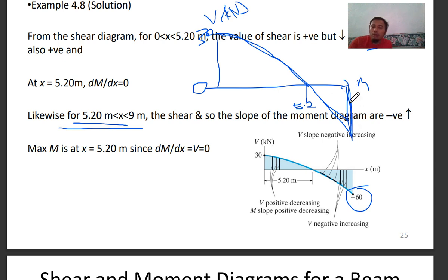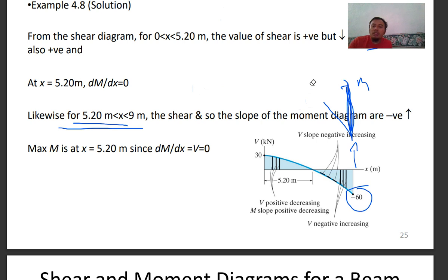So that's why there is a straight line upwards here, because of that 60. So this is your final graph. You can imagine the forces acting, and that's how the beam is trying to counter that force. You have a force acting downwards in a triangle, increasing, and then at the support it spikes up to achieve equilibrium.